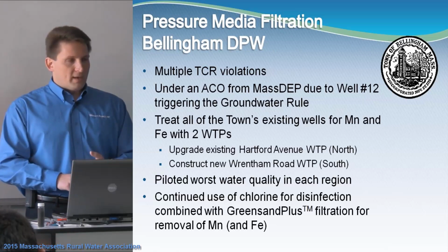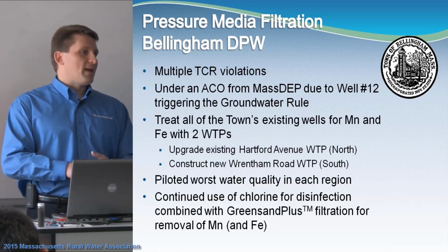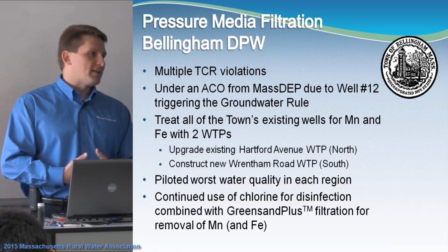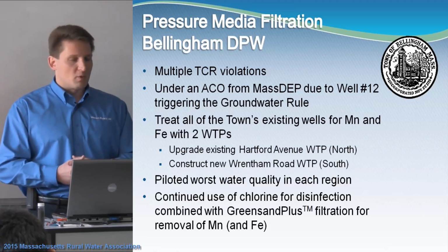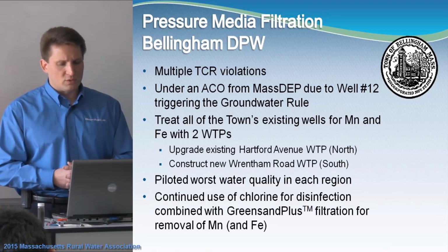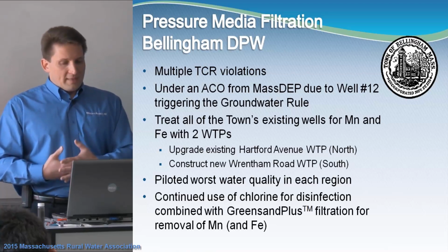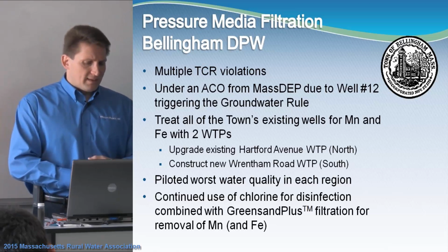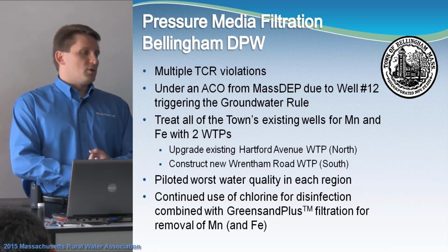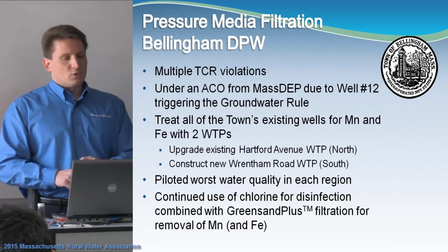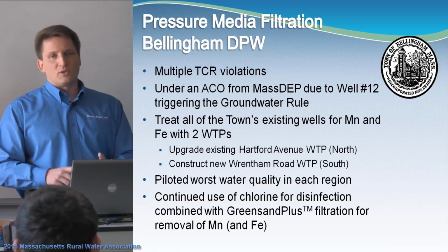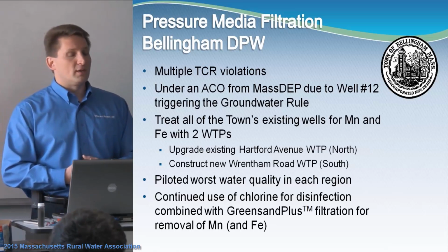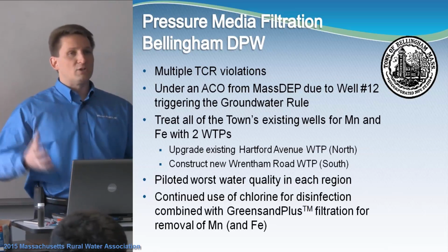And the problem with the chlorine, as we talked about before, is if you have the iron and the manganese in your water and you're not removing it, once you chlorinate it, you do create that problem. And they had significant consumer complaints throughout the distribution system. So at that point in time, we were hired to actually look at their system. We performed an exhaustive study looking at, could they go to new sources? Could they do interconnections? Could they sequester? Could they treat? And it basically boiled down that the most cost-effective solution was treatment for the entire town.